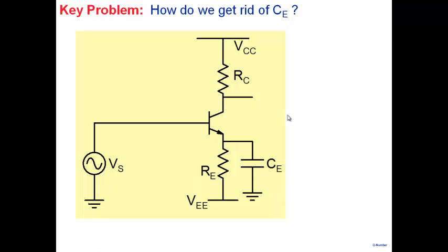So now think about what is the role that the capacitor is playing. Do you really need an element which is a capacitor, something which offers a 90-degree phase shift between current and voltage? Is that what you're looking for at this node? What is it that you're really looking for here? We've used a capacitor, but what you're looking for is something which offers a very low impedance path under small signal condition. That's all.